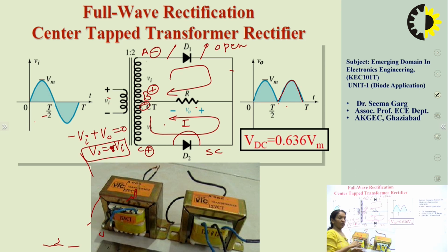So basically a rectifier is a circuit which converts the AC into DC, the bidirectional current into unidirectional, or you can say the alternating current into the direct current. But this current is actually pulsating DC, meaning it has many AC components superimposed on the DC component.